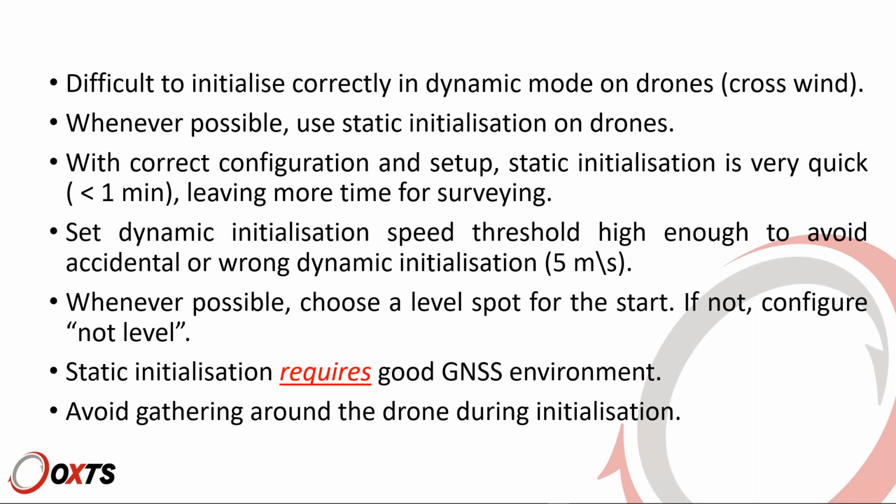If you do that with the correct configuration and setup, meaning you measure the distance between the two antennas accurately, and you tighten the accuracy on that to 1 centimeter, then static initialization can be very quick, under a minute, leaving you time for surveying. If you cannot initialize statically for any reason, or that is difficult, as a backup option, you can keep dynamic initialization, which will always be active on our systems.